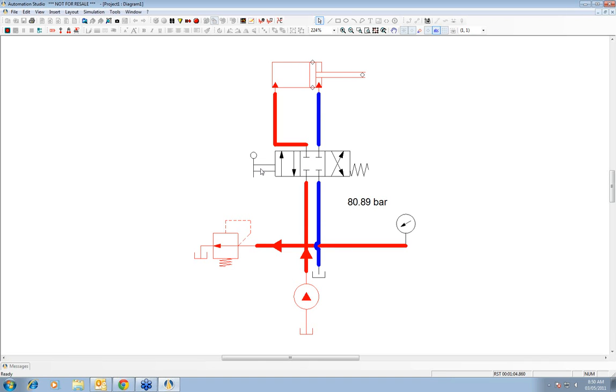Only by clicking on the commands on the side will it remove the forced state of the valve, okay? So whatever spool you want to simulate, you can simply click directly on it, and then you'll be able to simulate that position. And then to reset the spool position, you can simply click on the valve, and it's going to be reset.